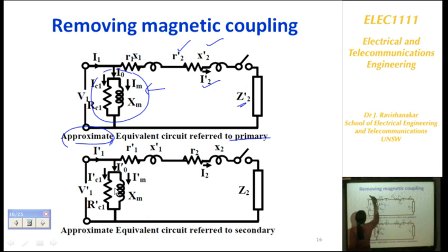The current flowing through the secondary now becomes I2 dash. There is the current I1 which is drawn from the supply into the primary. There is another current I0 which is drawn by the core, because we have seen that when the core has zero reluctance it does not take any current to produce the flux, but under practical conditions the core has non-zero reluctance, and therefore it will draw a very small current, say I0, in order to produce the necessary flux. So we have I0 here. By applying Kirchhoff's law at this point, I1 will be equal to I0 plus I2 dash. This is the simple equation when it is referred to the primary side.